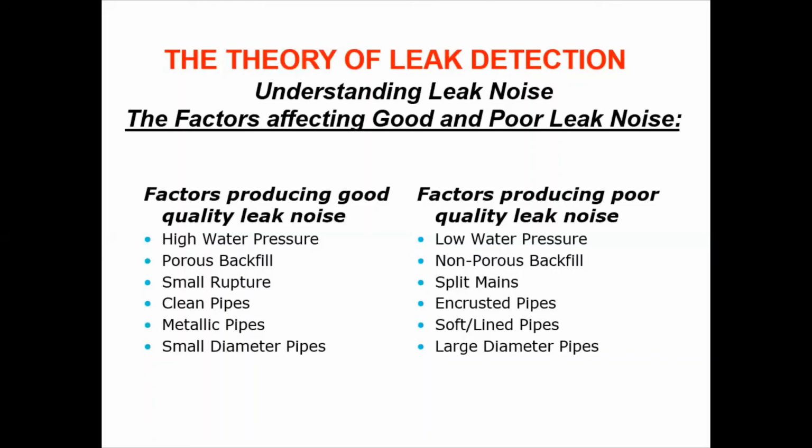Factors producing poor quality leak noise: low water pressure, non-porous backfill, split mains, encrusted pipes, soft or lined pipes, and then large diameter pipes.